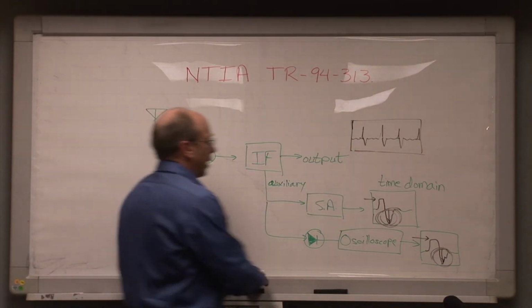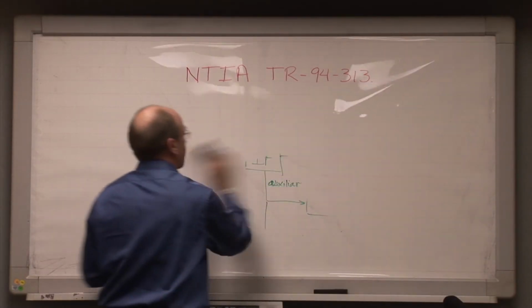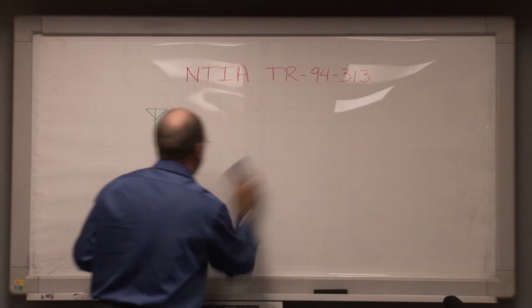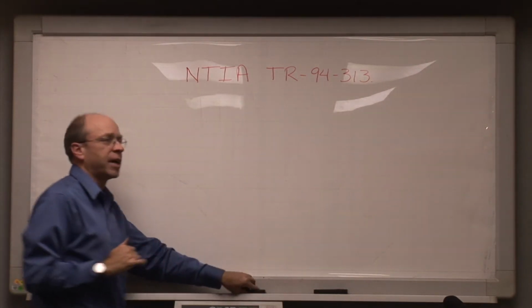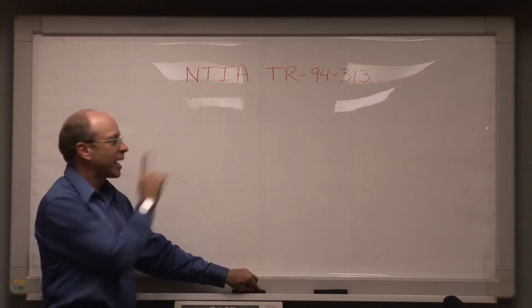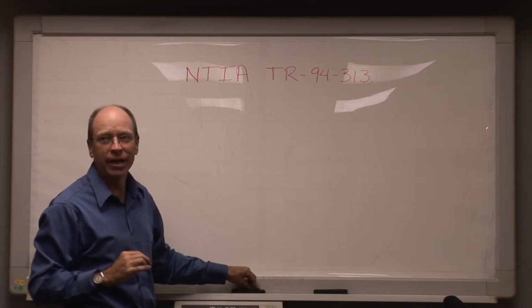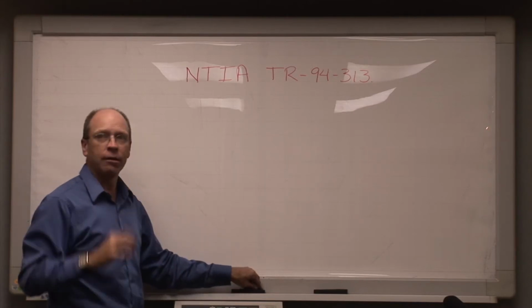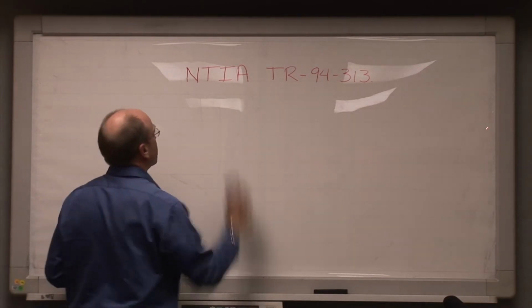So that is a check that you can do right at the receiver, assuming that you can get to its IF, and verify what's happening. Now, in a pathological case that I'll talk about next time, we saw that happening even though there was a bandpass filter at the front end of the receiver, and that's a different story. But it was, in a sense, front-end overload, even with a bandpass filter on. As I say, I'll talk about that more next time.